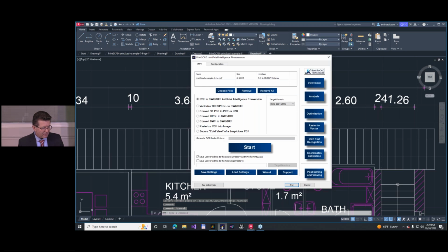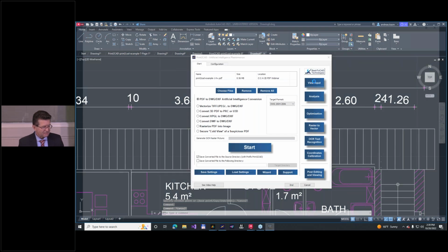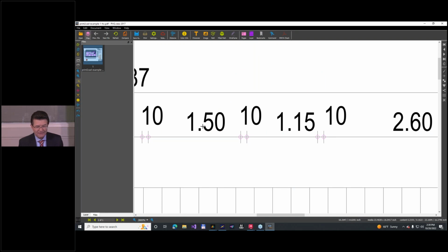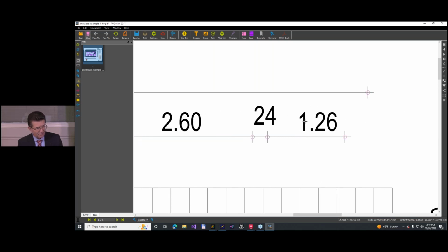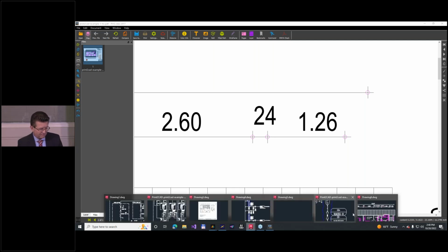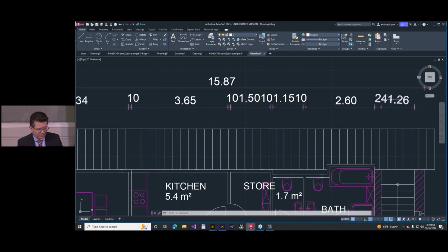See, the problem here by AutoCAD is that in this PDF file, every number is a separate letter. And AutoCAD has to bind, like our conversion software, this in text, and this in text, this in text. And if this is very close, it takes the text. Like, or if this is, for example, 24, very close to 1, AutoCAD makes an error here. Look, what's happened? It took 24, bound it together with 1, 2, 6, and now you can see it is.